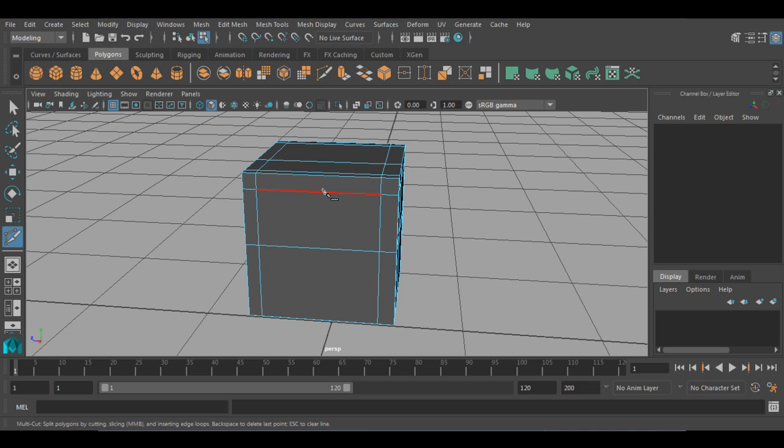So I want to create an edge between these two horizontal lines. You can see I'm highlighting those lines where I want to create a line. So you just need to hold left mouse button. You can see there is a point. If you drag the mouse, you can place the point according to your requirement on this horizontal line. You cannot go further with this beyond these vertices. So I want to place a vertex over here, and next line I want to create over here.